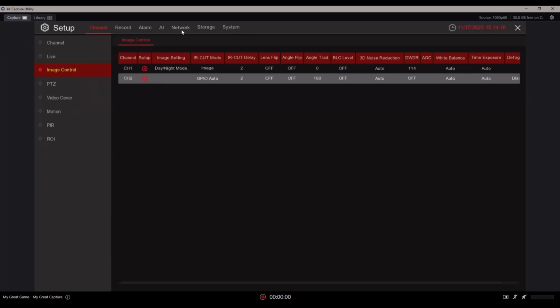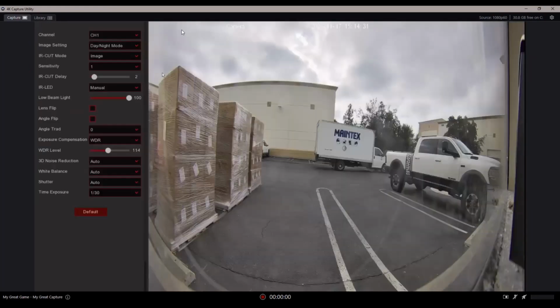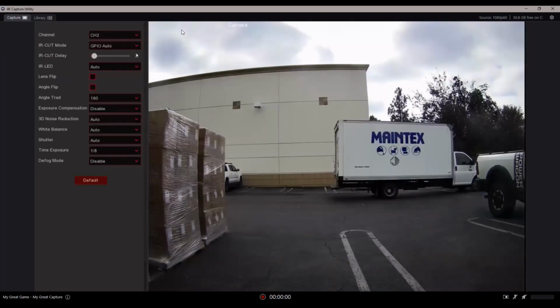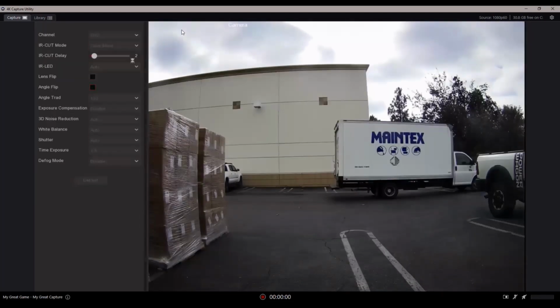Sure. Mike, this person's asking why their IRs are not turning on at night? It's a very good question, and we get a lot of those questions. We get a lot of calls saying, my IRs aren't working at night. Let me come back in here again. It's going to be one of two things. Either we have this stuck on day mode, right? Actually, let me come into this one here. We have this stuck on day mode, so the IRs are not going to come on.